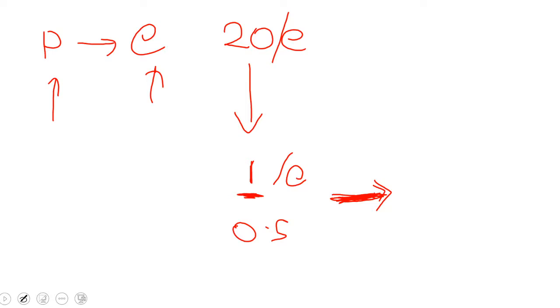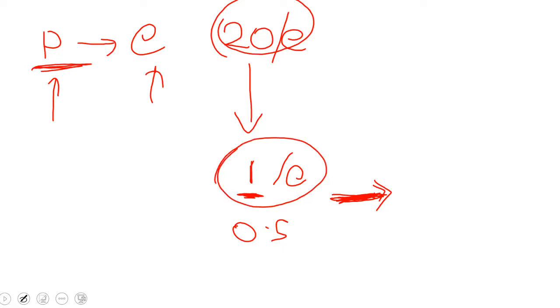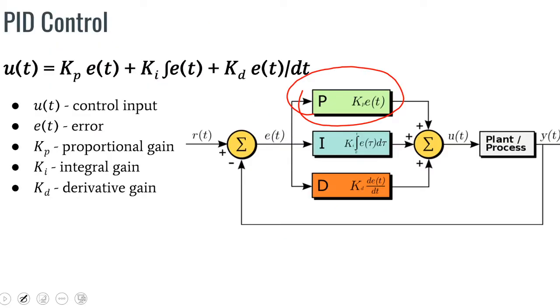When we have a higher proportion of error, the effectiveness of proportional gain is pretty good. But as we go further and further down, it becomes less and less effective. If the error is very small, the proportional application is also very small and not very significant. So at that point is where we are going to use what is called the integral component, or the integral gain.